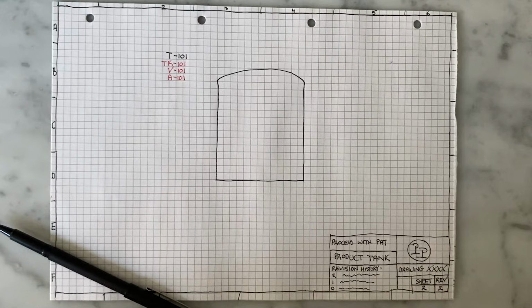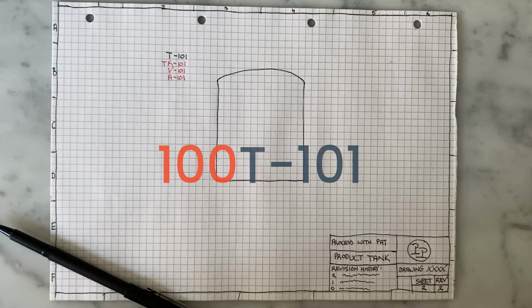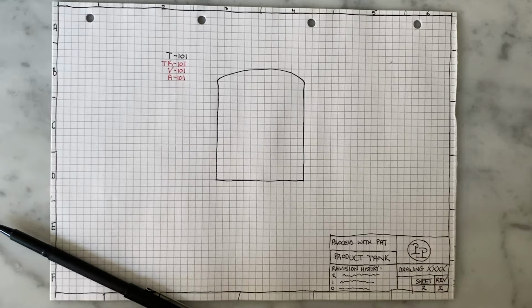Another common thing that happens, which I haven't shown here, is that the tag number is preceded by the unit number, especially if this is one plant on a bigger site. Apart from tanks, pumps, heat exchangers, distillation columns, reactors having tag names, all instrumentation, valves, transmitters, and so forth will have similar tags. The way equipment will be named and numbered and tagged is usually agreed upon by the customer, the plant that's going to own and operate this plant, and the engineering company who develops the drawings. And that's done right up front before the project even starts.